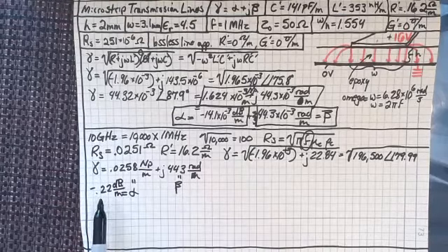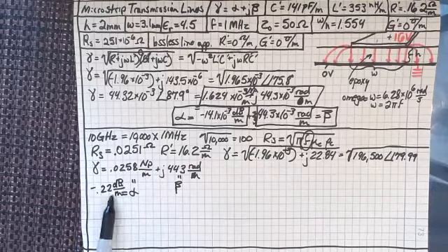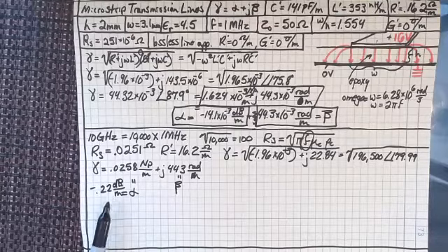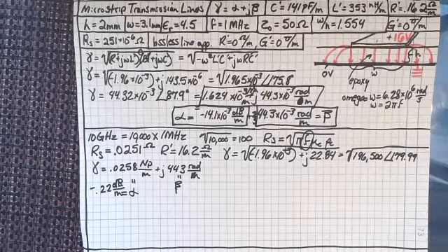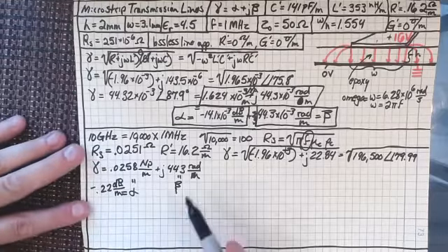Again, even at 10 gigahertz, we're still seeing that it's only minus 0.22 decibels per meter, and we're only going fractions of a meter. So we really don't have to worry about the attenuation constant when we're going over very short distances, like the inside of a spacecraft or something. Very short distances, we don't have to worry about that.